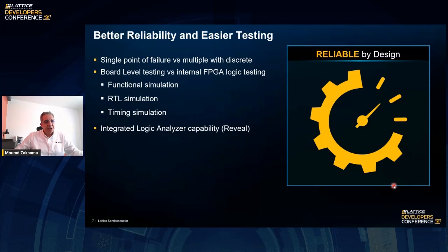So you can do it even early in the design process by using the simulation functionality that is integrated with the tool. You can do functional simulation to validate the integrity of your logic. You can do RTL simulation, timing simulation. And the nice thing about using the FPGA is all the timing is pretty well defined within the FPGA. So when you do timing simulation, you are pretty sure that your device will behave as expected, given that the simulation provides the right result.